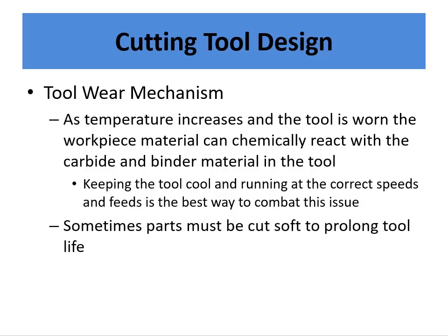So as the temperature increases and the tool is worn, the workpiece, depending on what it is, can actually chemically react with the tool. Okay, so heat is never usually a good thing. It momentarily softens the chip, and actually, if the heat can all go directly into the chip, it's actually a good thing.